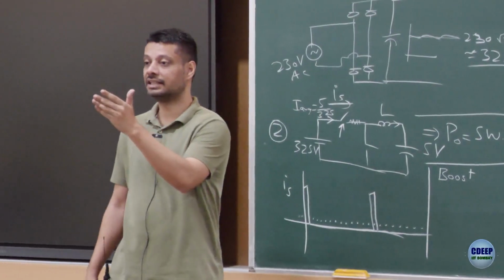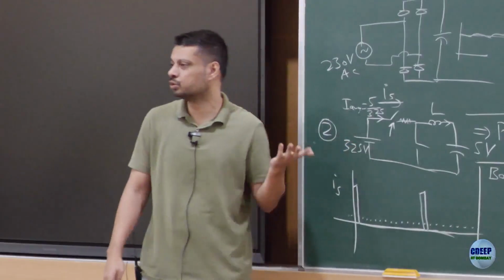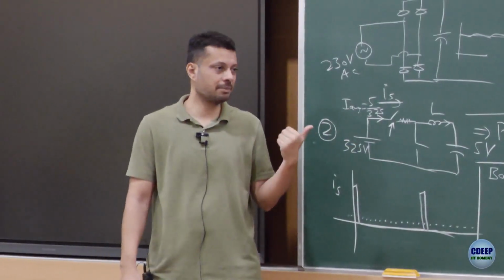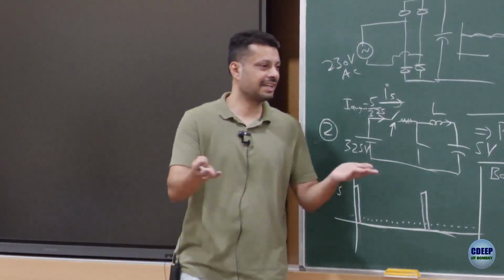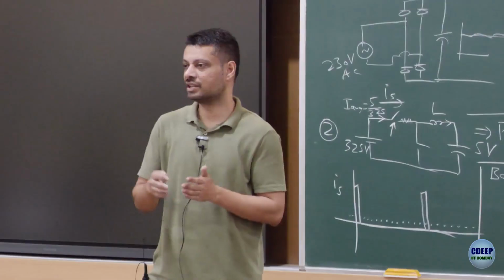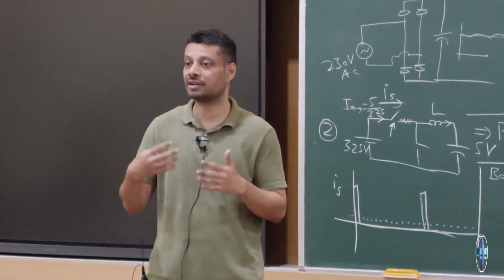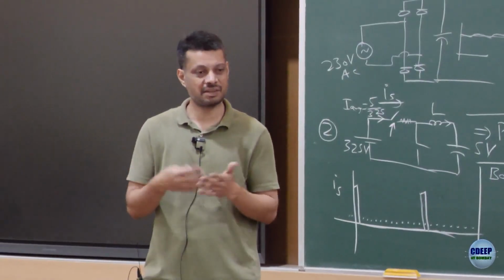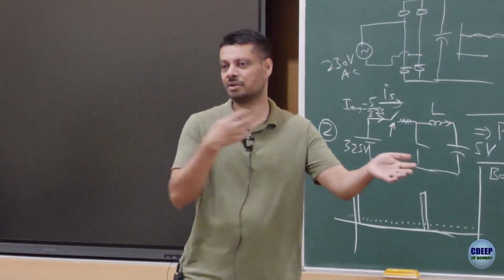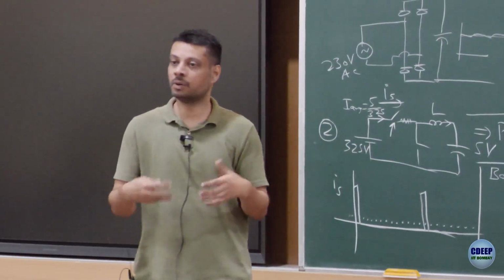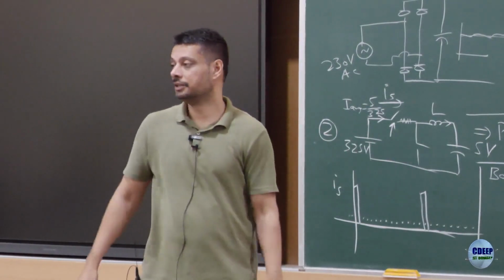By the way, the cascaded topology would also not work. Now you can make out why. If you are doing a boost, 5 times, 100 times, you have to do 5 into 5 into 5, right? You can imagine, it will be an unnecessary wastage of a lot of resources. If you do cascaded buck also, again, you would not really use a buck for a very large gain because the efficiencies would be very poor. So you would do 3-4 times buck, then again 3-4 times buck, and it just doesn't make sense. So what works is using a transformer somewhere in these circuits, right?